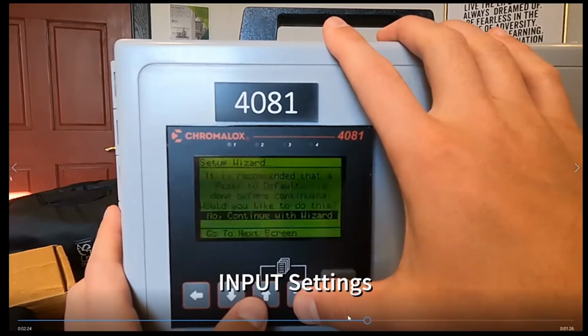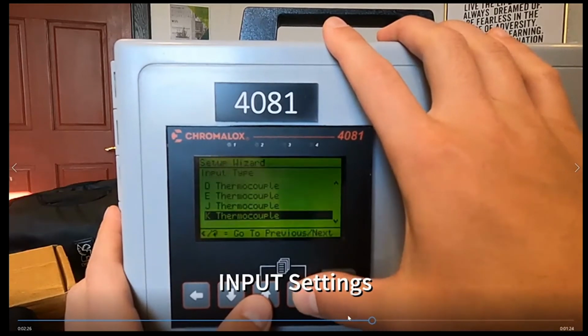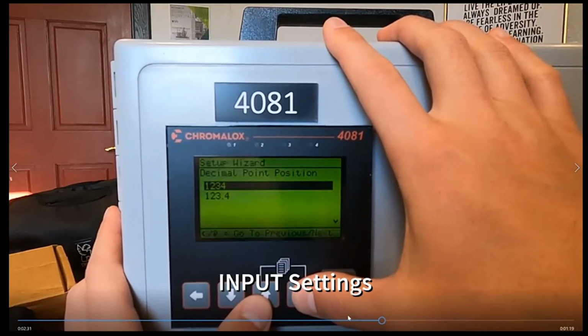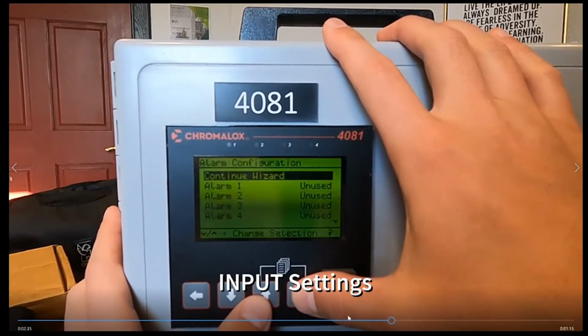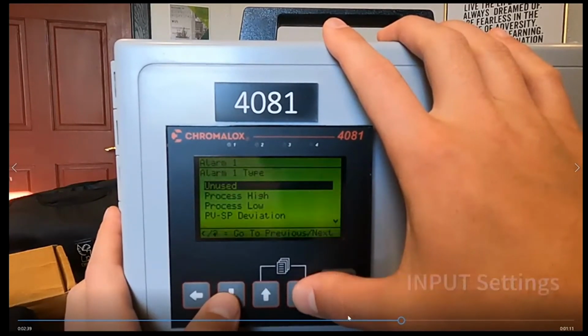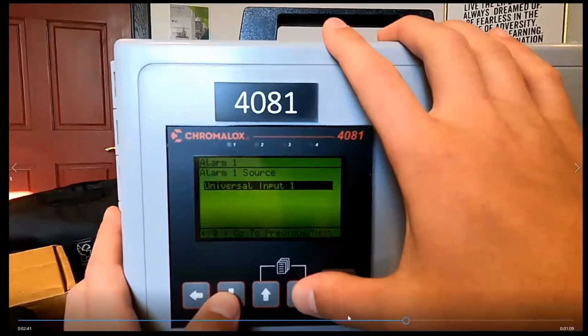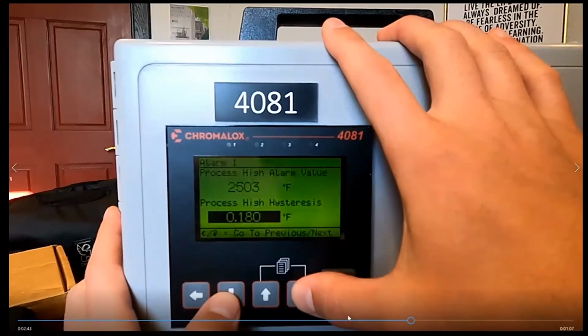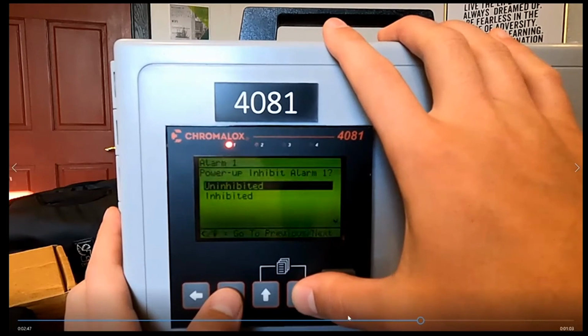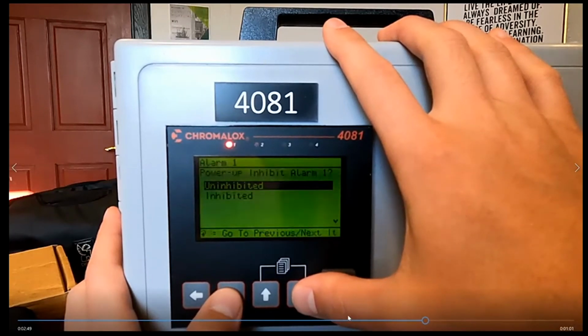Input settings, we know what those are. That's your thermocouples, your RTDs. If it's an analog setting, that's another point. You can obviously customize a little bit based on where you want your decimal point or how you want it done. You can have several alarms along the process. But again, it's still the same settings: process high, process low, duration, the length of the alarm, reset, locking. You can see me touching through that, which is really quick.